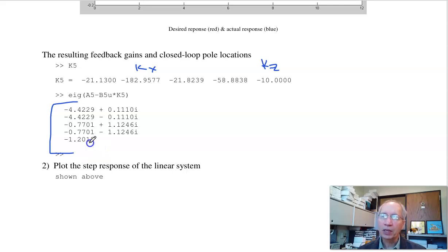What's neat about LQR is the dominant pole makes sense. I've actually got 3 dominant poles. The other ones, I don't really know where these belong. They drop out automatically. With pole placement, I had a problem because I didn't know where to put the non-dominant poles. With LQR methods, you don't have to worry about it. It drops out anywhere automatically.